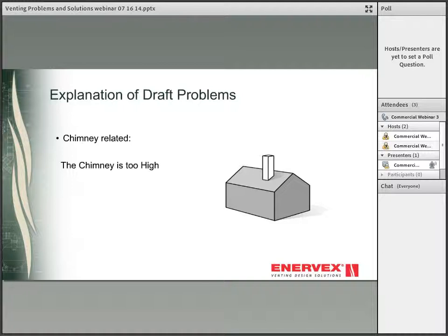Increasing the height of a chimney increases the draft. Draft increases in proportion with chimney height, but only to a certain point. At some point, additional height gives flue gases more time to cool. This problem can occur when the chimney is serving a fireplace in a multi-story building, let's say an apartment complex. A large part of the chimney is exposed to the outside. Possible solutions include reducing the height, insulating the chimney, or installing a mechanical draft system.